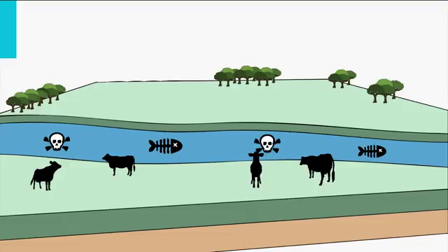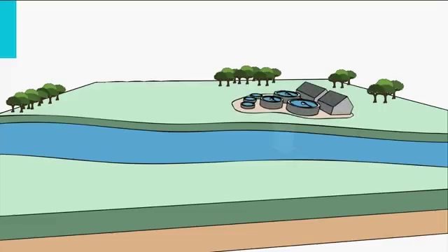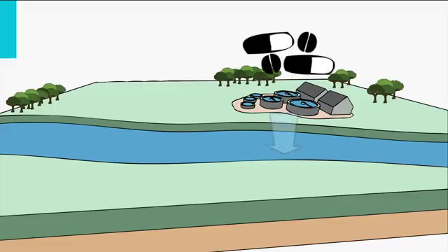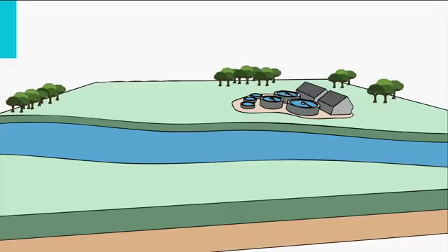In the past, the main focus was to remove organic matter from the wastewater, but more recently, advanced nutrient removal is applied to avoid eutrophication of the receiving water bodies. Future emphasis will be laid on the removal of endocrine disrupting compounds such as pesticides and pharmaceuticals to avoid accumulation of persistent organics in the environment.